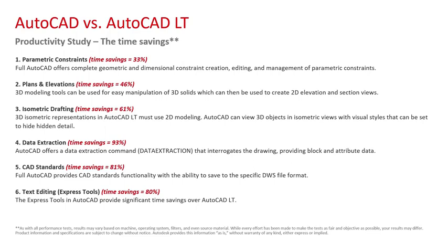CAD standards, again, another big time saver there, 81%. The CAD standards functionality is another one of my favorites, having been a CAD manager in the past, and it gives you the ability to save to a DWS file format that you can then compare against your DWG files. And text editing in the Express tools. Express tools are a lovely feature of the full AutoCAD, and again, a big time saving there over AutoCAD LT.